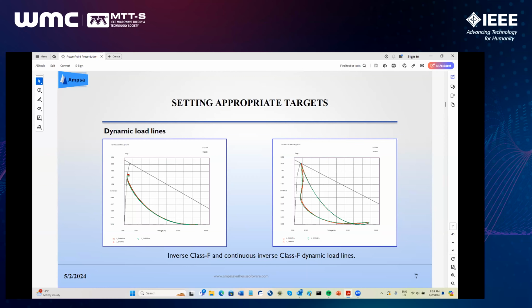And effectively this will also mess with your efficiency, because if you go there, the minimum voltage will be higher than in that case. So it's not always, it depends on where you chose the current. Now, important to understand, you don't have to make the current the maximum. With these boundary lines, you can drop the current to anywhere you want. You don't have to follow what the device can do. You can follow what you as designer want to do.